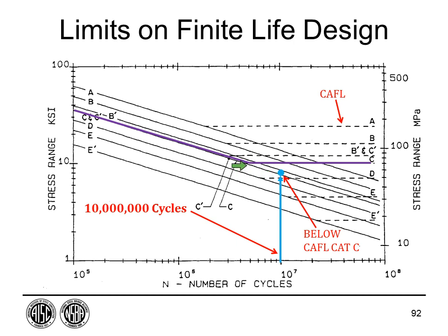So that's why the previous slide says there's limits on where the ADTT can be achieved. Simply this says is if you needed to carry 10 million cycles or more, in this case, you have to design for infinite life, or really anywhere in this region. You need to design for infinite life because you've run out of finite life.